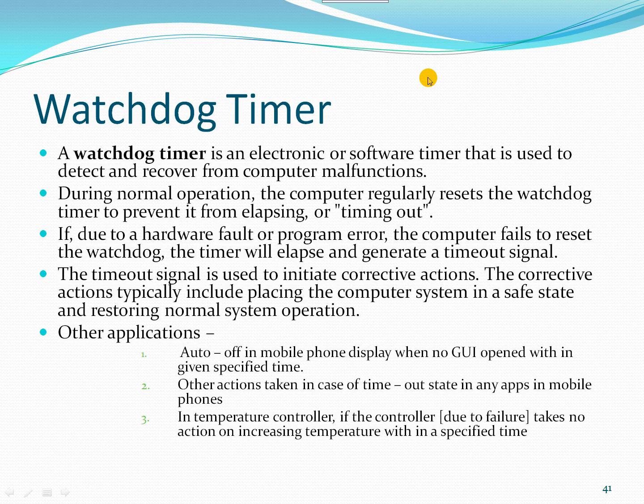And if any faults occur in the processor or in the hardware, or any program errors occur, because the Watchdog timers may be designed for software also, so if that particular software or the RTOS doesn't reset the Watchdog timer, then the Watchdog timer will think that the software or hardware for which it has been designed had an error.